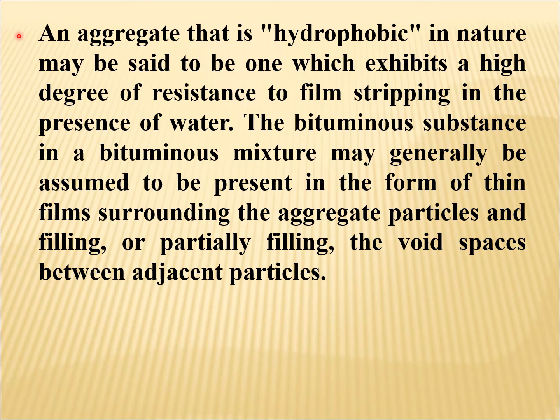An aggregate that is hydrophobic in nature may be said to be one which exhibits a high degree of resistance to film stripping in the presence of water. So obviously hydrophobic aggregates are good aggregates. The bituminous substance in a bituminous mixture may generally be assumed to be present in the form of thin films surrounding the aggregate particles and filling or partially filling the void spaces between adjacent particles.